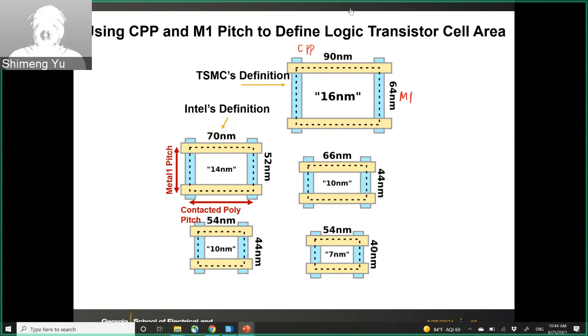Okay, you are asking about the physical design, like where to place those L1 and L2. I think different companies will have their own choices. So there's no unified design rule to say that this must be close to the L2 cache, or must be close to the ALU. This all depends on the overall design. So you can manually change the locations, and then you run the synthesizer, and you will see the performance impacts. I think those companies must have optimized for their workloads and target applications. There's no unified design.